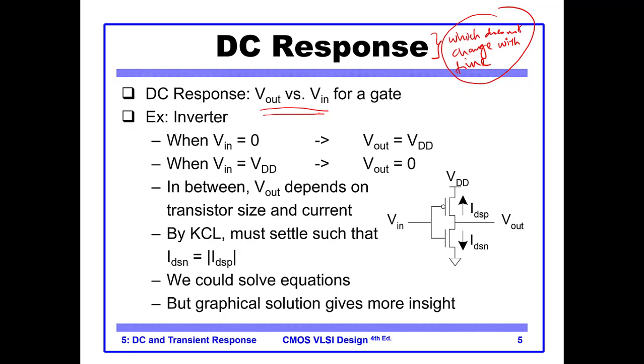So for example, if we consider a NOT gate, this is very familiar to you. A PMOS and an NMOS in series, and the gates are shorted. So if we apply a Vin of 0, so it is an inverter, the Vout is VDD. If we apply a Vin of VDD, the output Vout is 0.